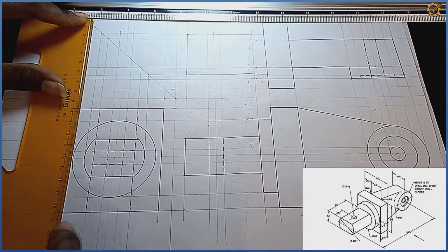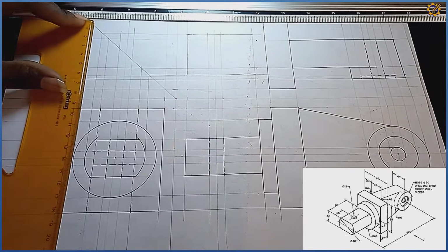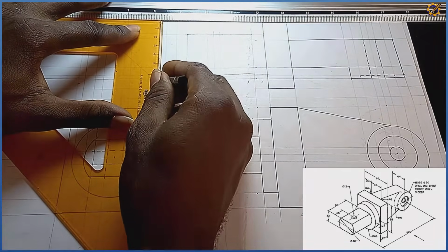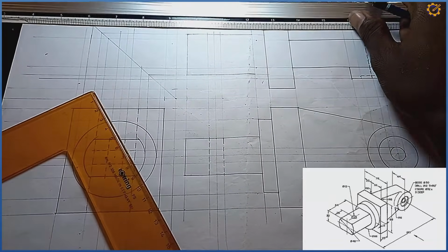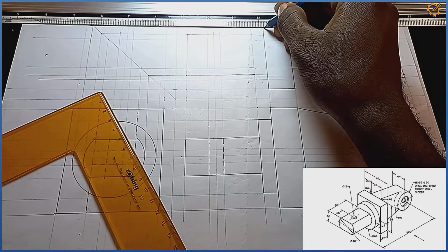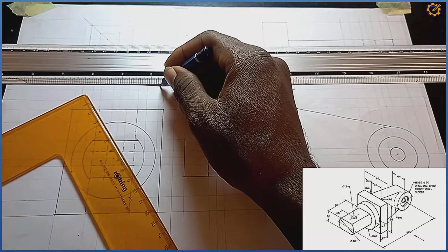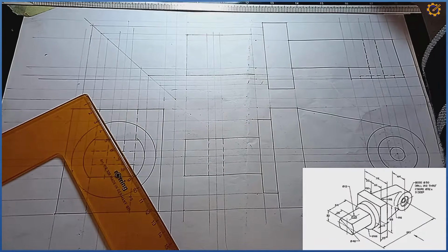Ensuring it touches that line of 45 degree here. Then on this area also I project this upwards, ensuring it touches this line of 45 degree here. So it touches this one right here. So from this junction I project horizontally till it gets here. Then coming here, this way it touches. So from here I project horizontally till it touches here. So what does that imply?